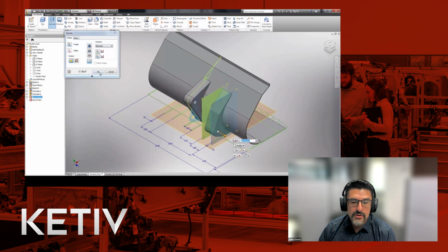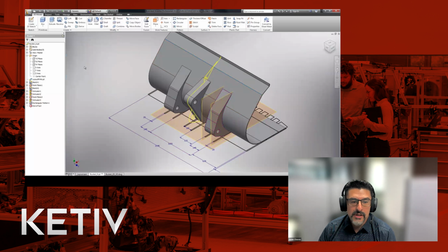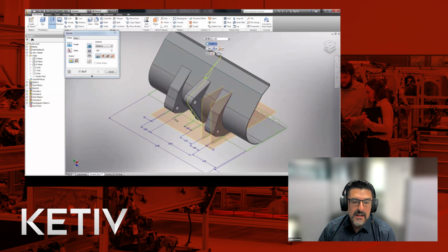So we're going to extrude from plane to plane to create more gussets here. And you'll notice that they're fairly chunky and big. We'll refine those as we go. But in each of these new pieces of geometry, we're creating new bodies, and we're working in a part environment. So it's important to note that, hey, this is one part, even though technically it could be an assembly. And if it's static, right, this is the best way to handle it.